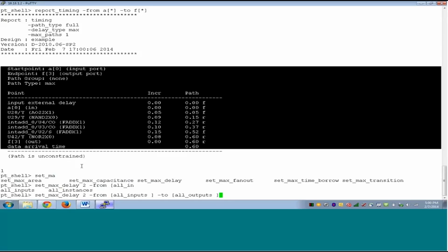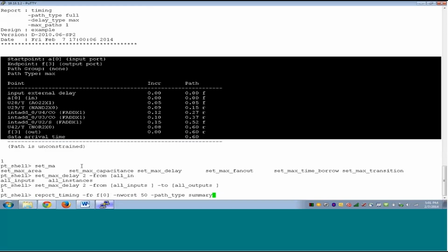Case analysis, on the other hand, allowed PrimeTime to do some logic analysis and switch off those paths, right? But false path is like telling PrimeTime, okay, please do delay calculation, but don't do any checking. And the same thing was happening in the first place. There was no constraint, so PrimeTime did not actually do anything. So we set a max delay constraint, whatever was used for synthesis. False path is already in place.